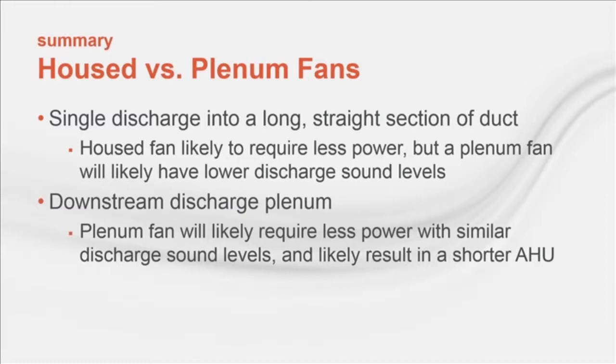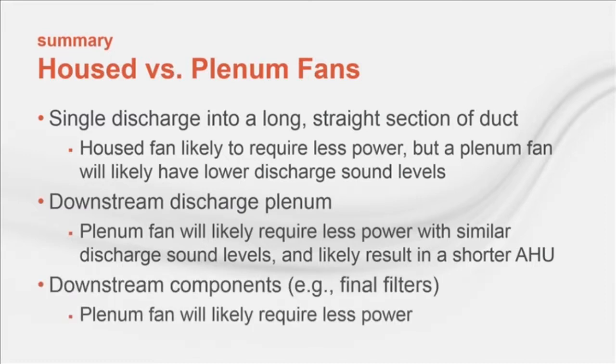When downstream sections are present, such as a discharge plenum, final filter, gas heater, or even a blow-through cooling coil, a direct drive plenum fan will likely require less power than either a housed or belt-driven plenum fan.